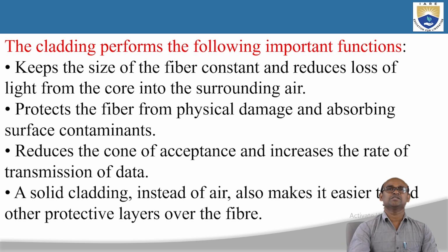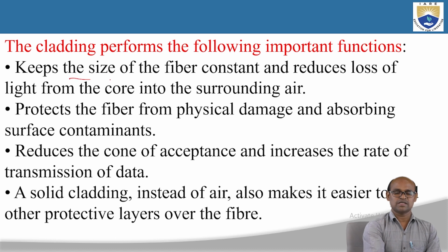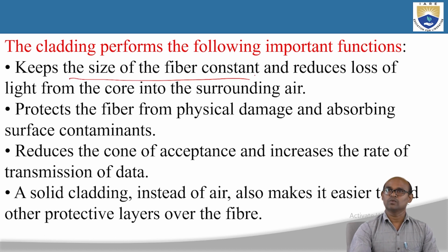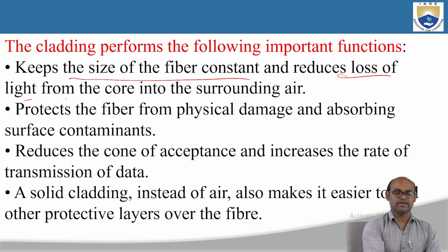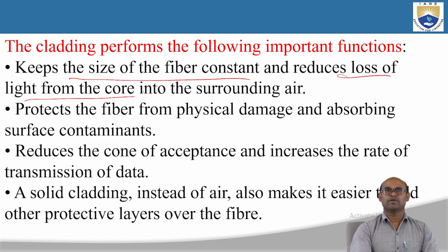So the question is, what is the importance of cladding? The cladding performs the following important functions: keeps the size of the fiber constant and reduces loss of light from the core into the surrounding air. The first point is that cladding is going to keep the size of the fiber constant. And it reduces the loss of light that is going to escape from the optical fiber. Very important advantages.